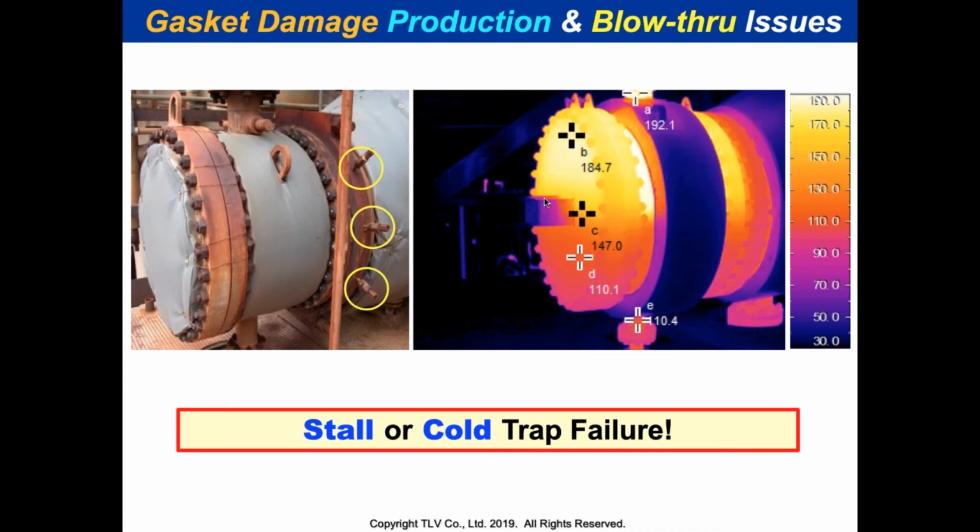Why are you talking about that on your condensate line? Because when that happens, they're also going to open the bypass, and that's the double whammy. They get hammer on the inlet side, and they get steam going into the header on the outlet side. It's the double whammy situation. So when you walk through the plant and you see a leak collar, and you know you've got stratification on your heater, that is a high value opportunity to fix, because that is a double whammy.